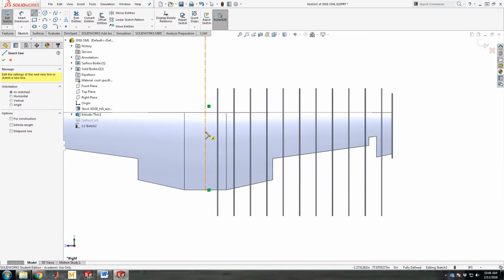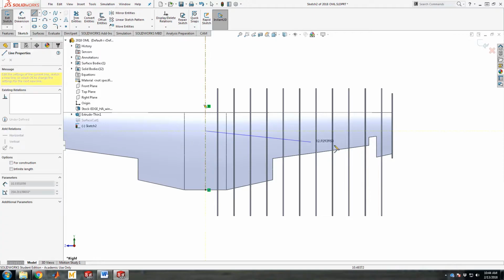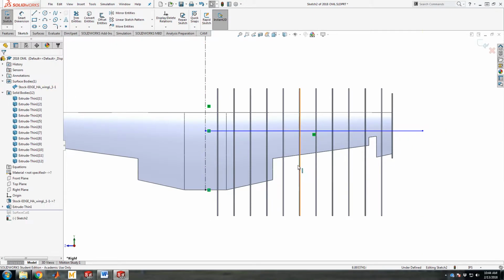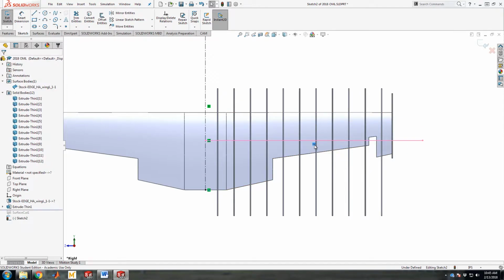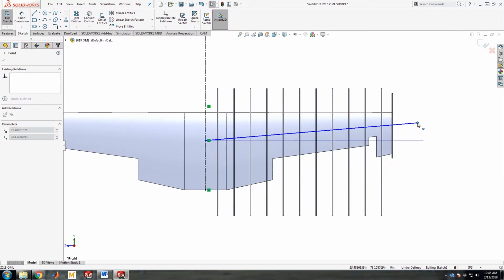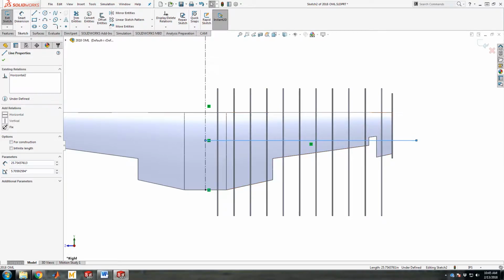Sounds good. For the spar, you could go through here and measure the exact quarter chord, but yeah. Notice because it's tapered, this actually has a forward swept quarter chord. So it's a little bit structurally unstable if you want to look at it that way, but you could justify putting the quarter chord there, you could justify putting it back here, you could justify not even making it straight, and you could keep it at the exact quarter chord of the wing, which probably looks something like that-ish. But I'm going to go horizontal. Okay. So that extends a long way that way.